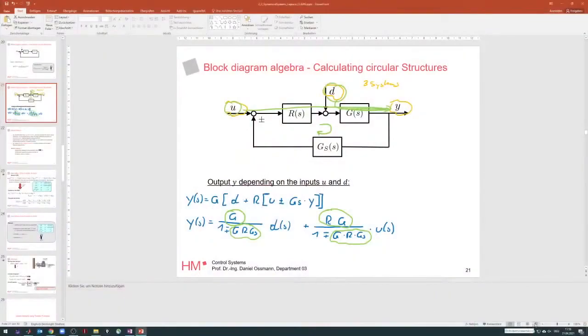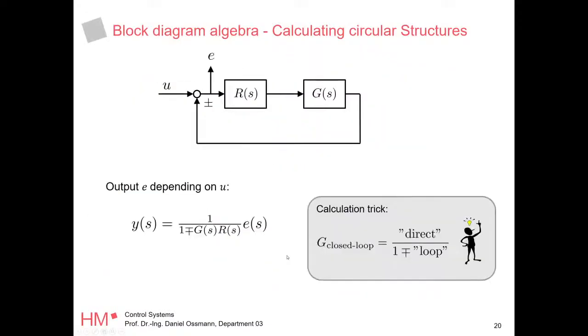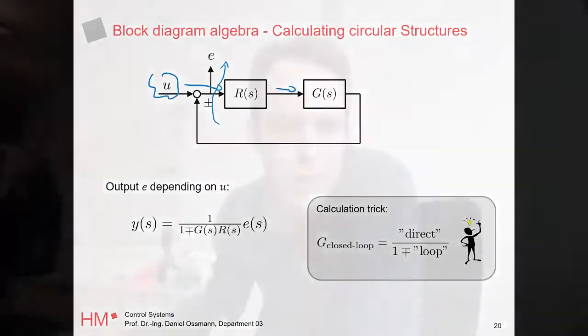And in that regard, I showed you last time the Laplace domain, right? We introduced it and figured, okay, there's this nice thing about the block diagram algebra, where we can not only make use of it, but there's actually a mathematical meaning behind it. We can have signals propagated through a system and lead to an output. This is not just any arbitrary drawing I like to do, it really has a mathematical meaning, because we can just think of multiplication and addition of signals.